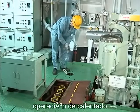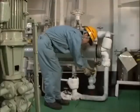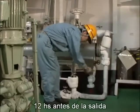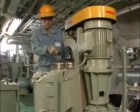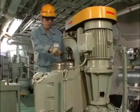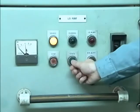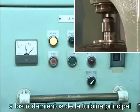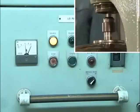Now let's look at the actual warming up operation. Start lubricating the oil purifier 12 hours before departure and heat lubricating oil in the sump tank. It's necessary to supply lubricating oil with appropriate viscosity to main engine turbine bearings, reduction gear, and so on.